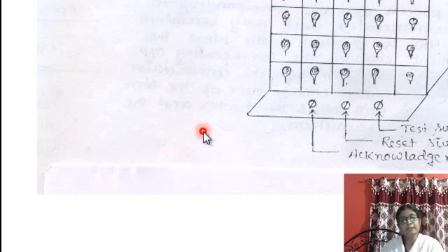That means whenever any fault occurs in the process, that failure should be acknowledged and registered by the plant personnel. So in order to generate the error signal, an audio-visual alarm signal is generated, and that is done by the device called the annunciator. When a particular process variable exceeds the desired limiting value, the annunciator produces the corresponding alarm signal.